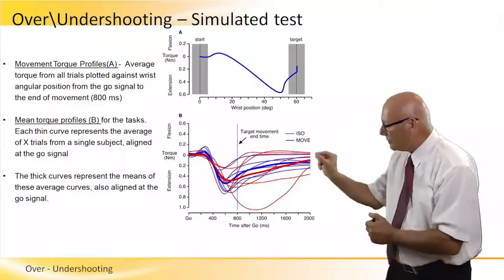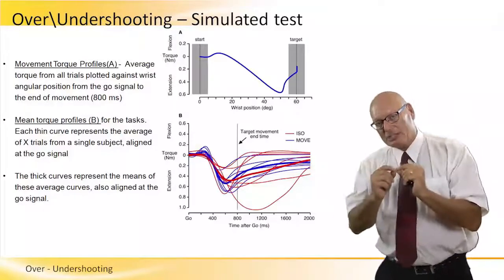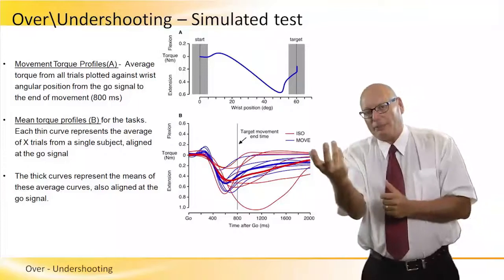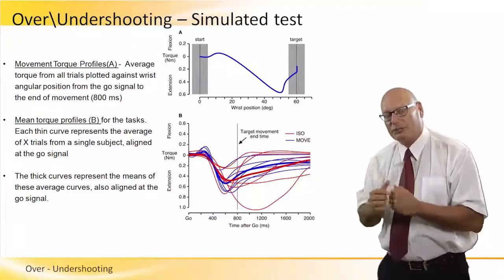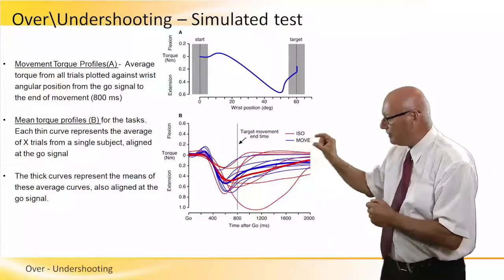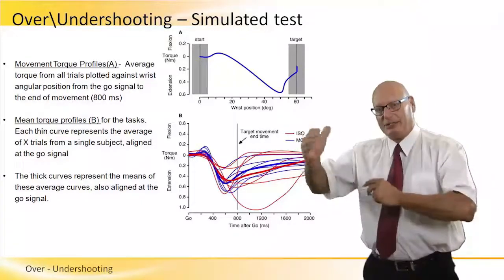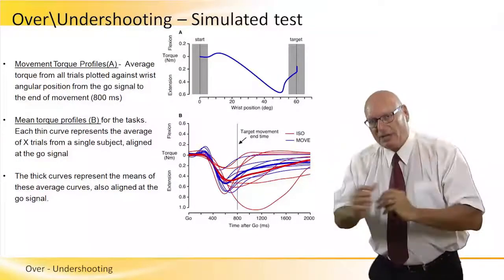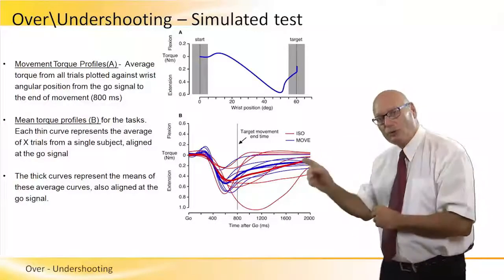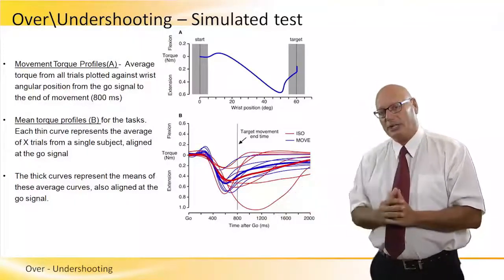That's because 10 degrees before the end, we change the speed of the path, we change the position of the gripper in order to reduce the torque, and that particular part between the degree number 50 and the degree number 60 is what we call the soft landing. You have to keep in mind, for every movement of the robot, there should be a graph like that in order to assure a soft landing.